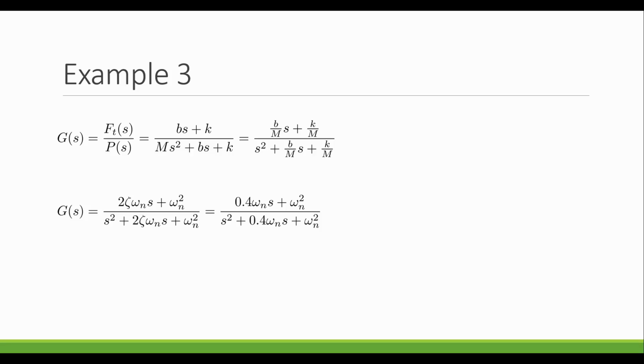So now I have this expression. Now I don't have enough information to know the natural frequency. Again, we're going to be finding what that is because we're going to be setting the spring constant, but right now I don't know what it is. So I can't at this time take my G of s expression and put it in to make a Bode diagram because I have this variable in it, omega n. So this is the step where we know that we probably need to use a relative frequency Bode diagram. We can't go down the same path we did in the first two examples. So this is the kind of splitting point where we're going to solve this a little bit differently.